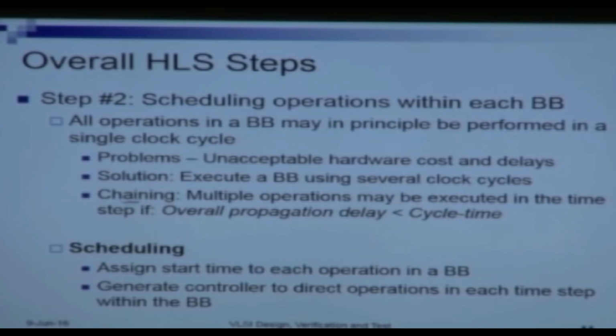So what is chaining? Multiple operations may be executed in the same clock step if the overall propagation delay of all these operations together is less than a clock time, the cycle time. So therefore this only complicates the scheduling problem itself. Okay. So what is scheduling as such?